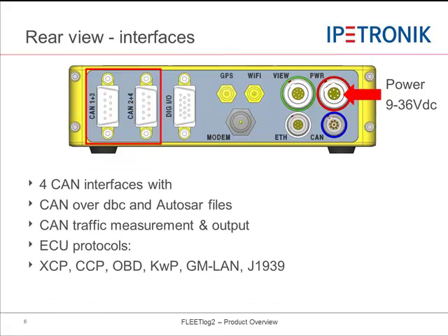The 4 CAN interfaces supporting CAN DBC and XML file imports, AUTOSAR description file imports, and protocols like XCP, CCP, KWP, OBD, Diagnostics, UDS, GMLAN, J1939. You can also perform CAN traffic measurements with filter functions and CAN traffic sending functions.